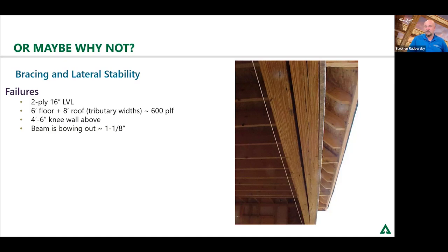Let's say it was a cathedral ceiling. Depending on how it's attached, and if the upper plates are there to help with bracing from an engineering standpoint, that upper plate can actually do it. The only way to solve this for this instance would probably be to put horizontal, or actually diagonal, kickers in the garage door opening to help stabilize.